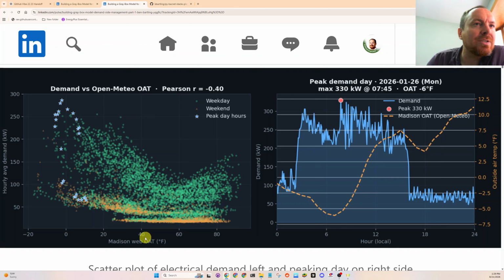And then I was almost kind of curious to see, at some magical moment in time below 10, 20, or 30 degrees Fahrenheit, when you would just run the building 24/7. The idea would be that you'd shave off these startup events. So if you got your demand down from 285 to 200, you could run the math and economics on what that would save you in demand penalty all year round. And for some buildings, that could be a big chunk of change.